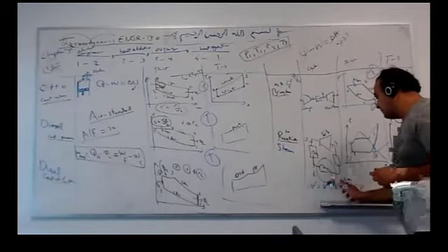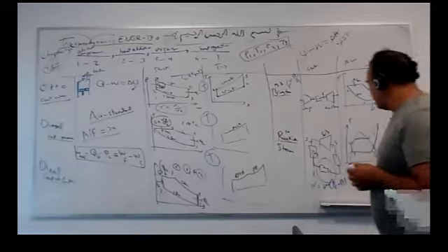We don't need the change in enthalpy here. Why? A pump is a device that compresses liquid. Incompressible liquid means the specific volume does not change. That's a good advantage. We can use the reversible work equation, which is W equal to integral of V dP, to get this. This only happens for open system, steady, and reversible. This goes back to chapter 7.